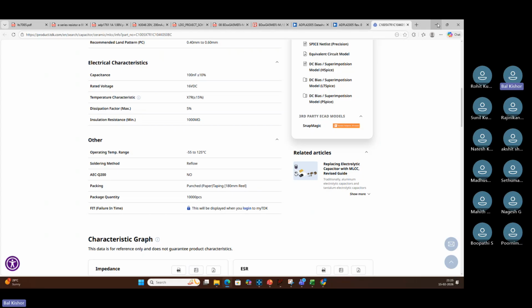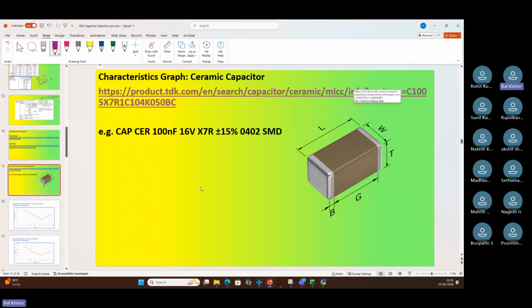It won't cause a problem because you are not operating the capacitor at 300 degrees centigrade all the time. It has the capability to withstand 300 degrees centigrade for, let us say, 5 minutes. Within 5 minutes you will be able to solder the capacitor. I don't think 5 minutes is needed; it's too easy. The time the capacitor sees 300 degrees is very much less than that.